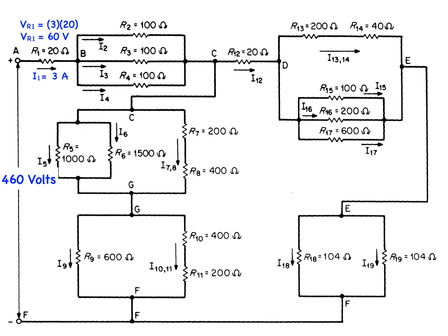Because the current must split equally into 3 identical resistors, which is Kirchhoff's current law, I4 must equal I3 must equal I2 must equal 1/3 times 3, or 1 amp. Again, using Ohm's law, the voltage drop across R2 is 1 times 100, which is equal to 100 volts, which also equals the voltage drop across R3 and R4.